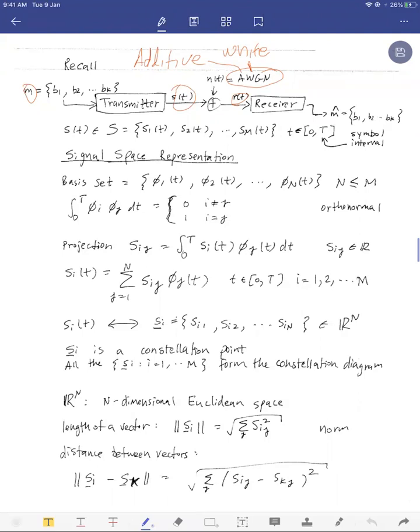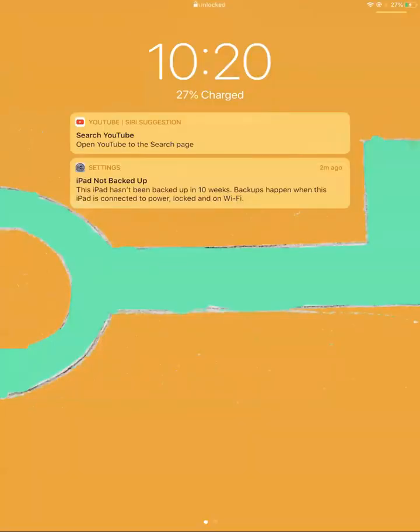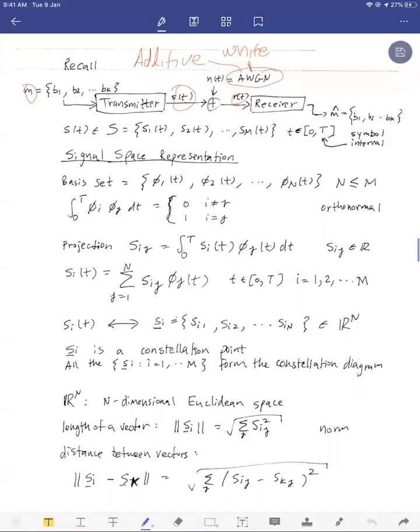So since the power spectral density is the Fourier transform of the autocorrelation, when the power spectral density is flat, it means the autocorrelation is a delta function or impulse. And if the autocorrelation is an impulse, what does that tell you about the process? It means that it's uncorrelated in time, that the samples are independent. Right? Okay. And that's good because that's a good property of noise. There's no reason why noise from sample to sample should be correlated. Okay, so again, getting back to, we're talking about white here.